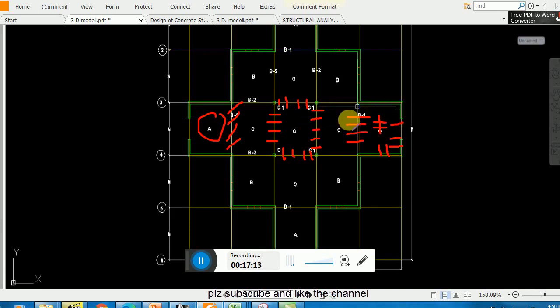And you see the effect of discontinuity as compared with the continuous. Okay, here all edges are discontinuous, so you see there the moment is larger, the maximum one, as compared to all panels. And here you see all the edges are supported, all the edges are continuous, so there will be a little bit of effect on the positive, but here is the most larger effect. So that's why the spacing should be minimum in the negative moment region, and should be minimum in the positive moment region. This is the critical analysis. If you are working as a site engineer, you must report these things, clear.